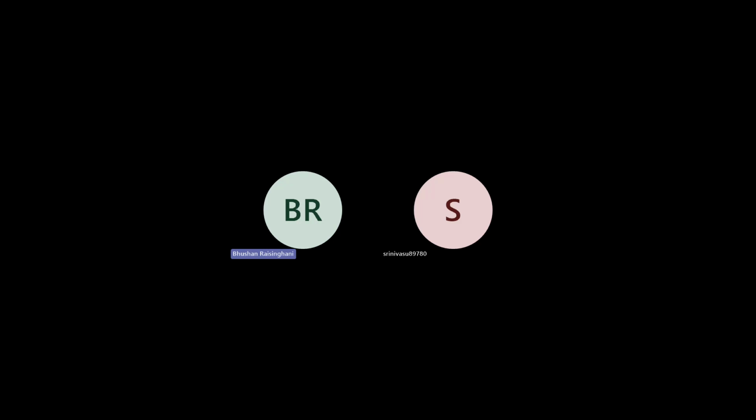In the Indian standard, there are no plain shear walls considered. So we can refer to the analysis of plain shear walls from the ACI code. That very well explains how to analyze or find the PMM curve for the plain shear walls. So plain shear walls are the walls having a web and top and bottom flanges, what we say C type, T type, L type, F type. All those shear walls are called the flanged shear walls. So that design has to be seen from the ACI code. And rectangular shear wall analysis or design is given in IS 13920.